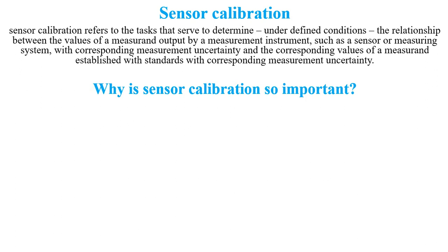So I can just take the sensor that I've bought, read the value on something that is frozen, that we are certain has reached the freezing point. And then we read the temperature of water or anything that we are sure has reached the boiling point. Then we can come up with a formula that determines the temperature values based on the range we got from our readings. Then that formula is now used to get the actual values.